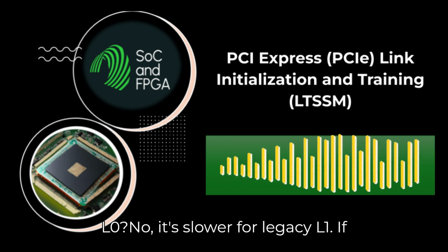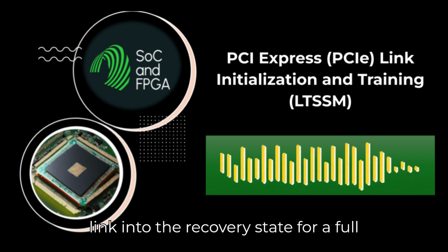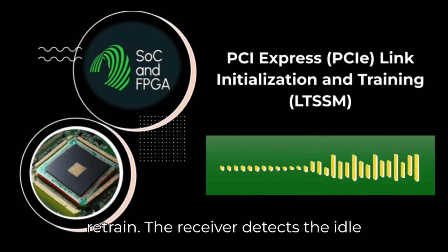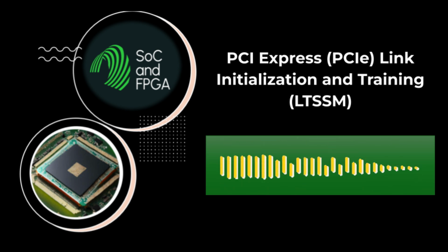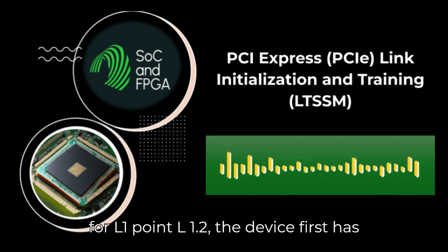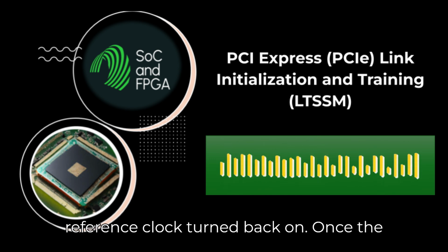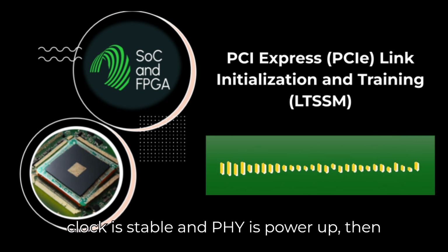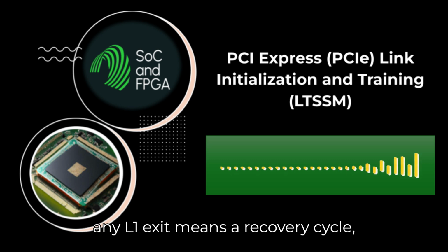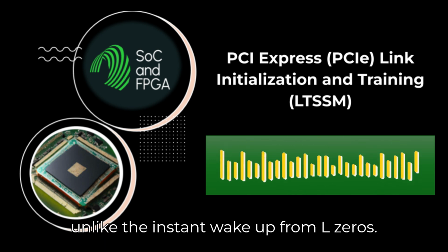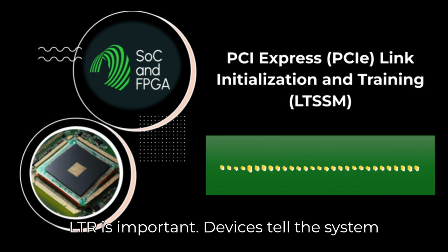For legacy L1, if either side needs to send data, it triggers an exit, but this forces the link into the recovery state for a full retrain. The receiver detects the idle exit, often a TS1, and jumps to recovery. For L1.2, the device first has to reassert CLKREQ# to get the reference clock turned back on. Once the clock is stable and the PHY is powered up, then it goes into recovery for retraining. So any L1 exit means a recovery cycle, unlike the instant wake-up from L0s. That's why latency tolerance reporting, LTR, is important.